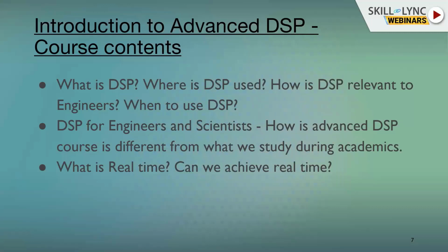Okay, and then I have to complete the processing of that wireless signal within the 2-millisecond window. I'm going to take 2 milliseconds to compute what is present in the wireless signal, decode the data, and give it to the next layer. For example, it could be a MAC layer, or the next higher layers.